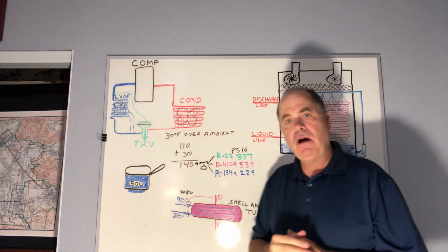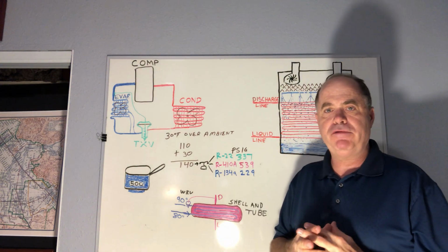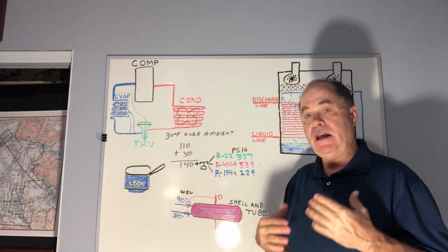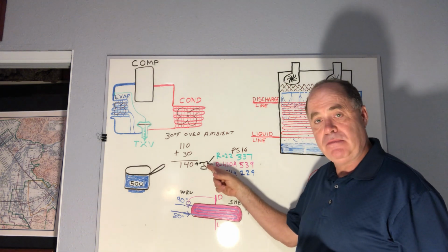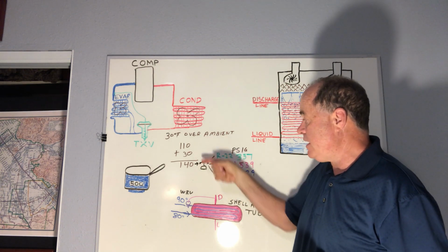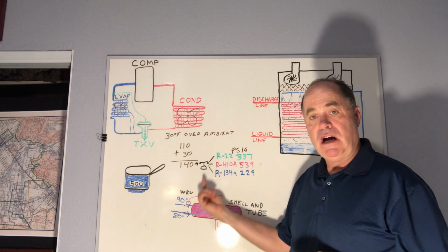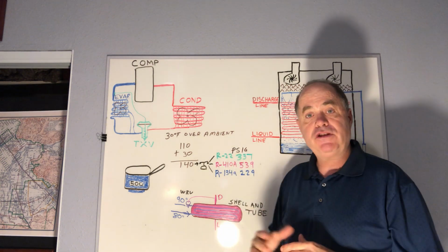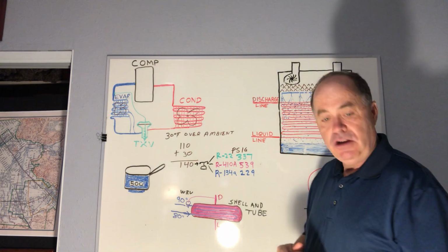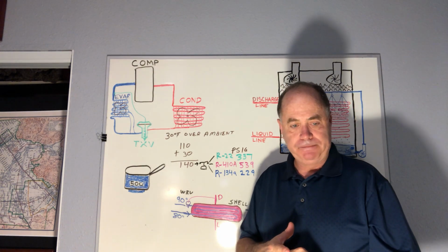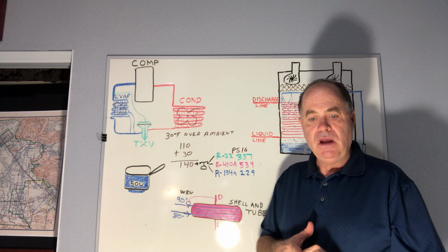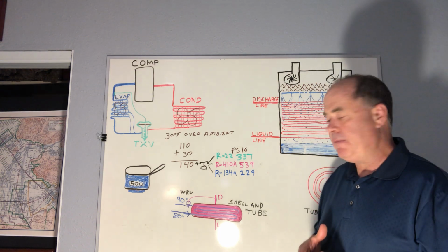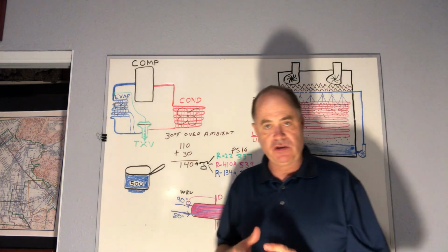So these are approximate places where the refrigerants should trip out on head pressure cutout, which is here. The symbol for a high pressure cutout is right here, opens on a rise in pressure, shutting off the circuit, protecting your compressor, okay?